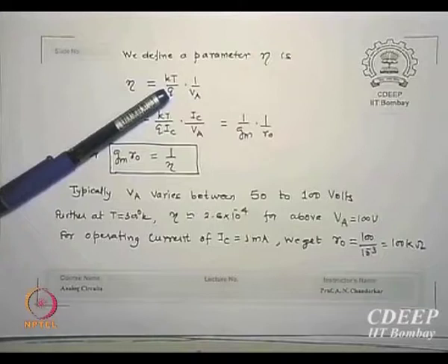So I actually search for transistors which have smaller etas, that means larger GM R0 terms. So when I go into the so-called manuals of transistors and I am looking for higher gain bandwidths, I should look for transistors which have higher GM R0, essentially smaller eta values. These are all specified as figures of merit. Is that point clear? Someday you will design a chip or circuit and open a manual from a company, and you should know what to look for. That's why I showed you.